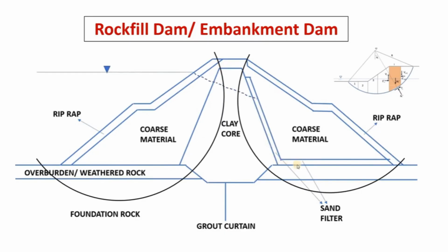This can be done by hand calculations. But nowadays, Slide software is there and other software is also there to reduce the time and effectively compute the factor of safety. Here also, for different cases we have to do the stability, such as steady state seepage condition, sudden drawdown and so on.